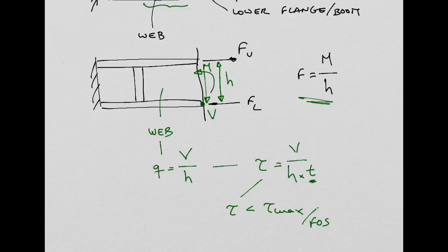Now, in aircraft, because we're always trying to reduce weight, we design these webs not for yielding, but for buckling, yeah. And that's when we say that we are using a thin web for the spar. So basically, we will allow buckling to happen, but in a controlled way. And that's what I want to show you next, what is going to happen. And the best way I found to show you that is to give you an analogy. So I'm going to try to represent that analogy here.